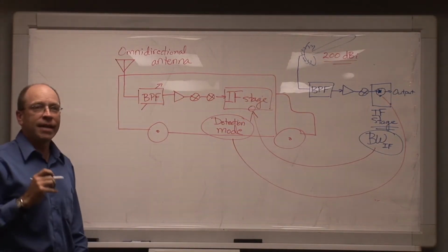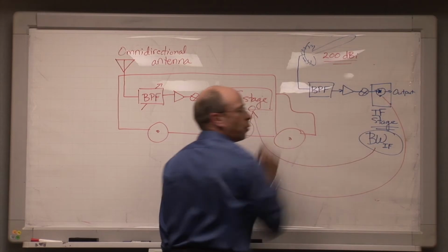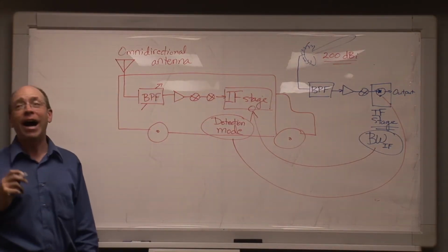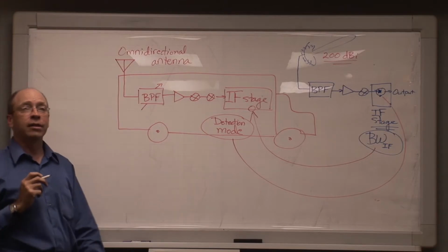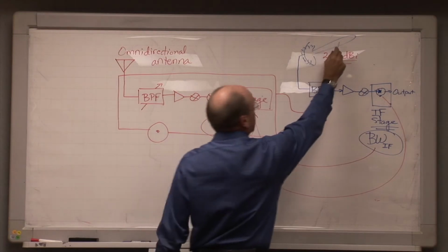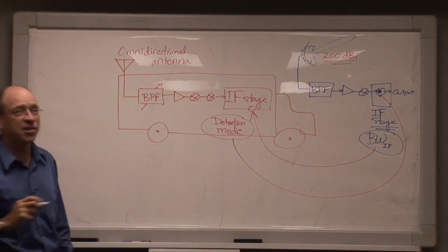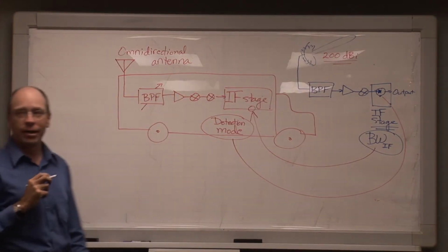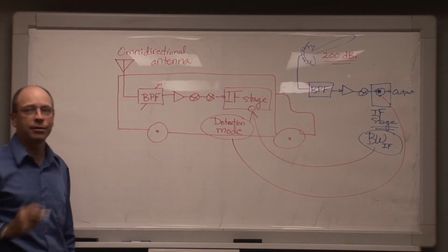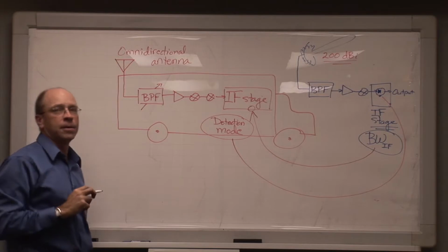What are the chances that that interference source is getting into that beam, which is a fraction of a degree wide? Not very high. And in fact, what if they report that the interference typically goes on for minutes or hours at a time? Well, I can pretty much guarantee that nothing is hovering in that beam for more than about a second. Maybe an aircraft at 100 miles distance might fly through that beam momentarily, but nothing's going to hover in that beam other than some helicopter for minutes or hours at a time.